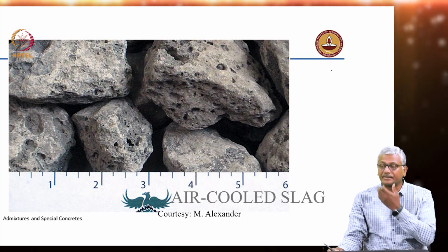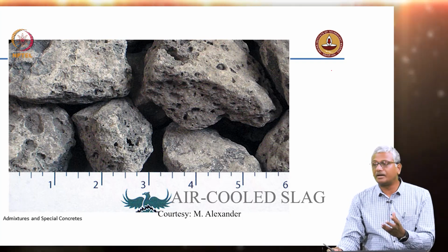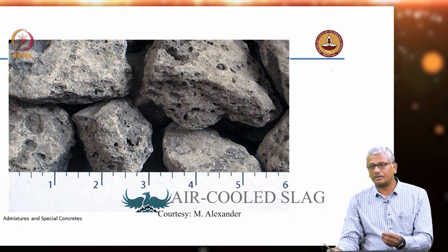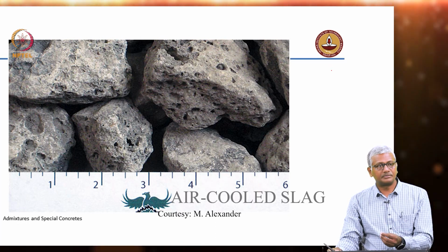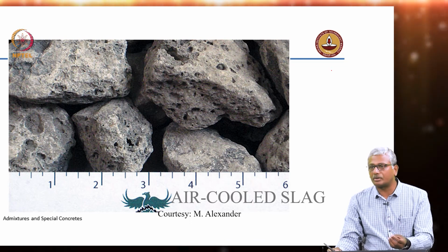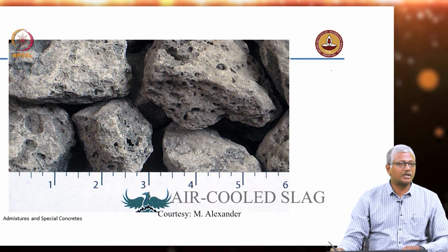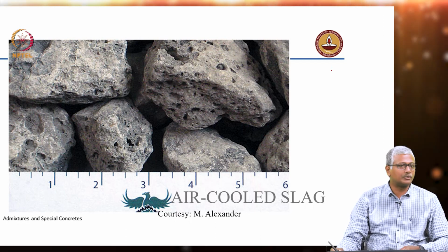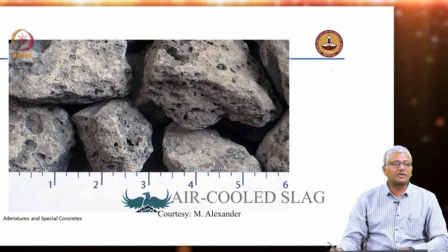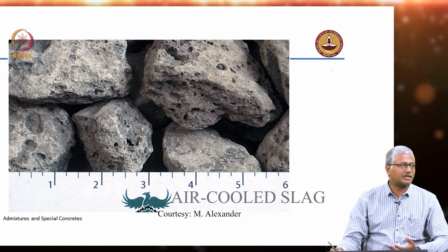And air cooled slag is a material that is fairly hard and can be quite useful as an aggregate in concrete. Only problem is slag is a material that may have a large iron content, obviously from the process of removal of iron from iron ore, and because of that it may also contain significantly high iron content.